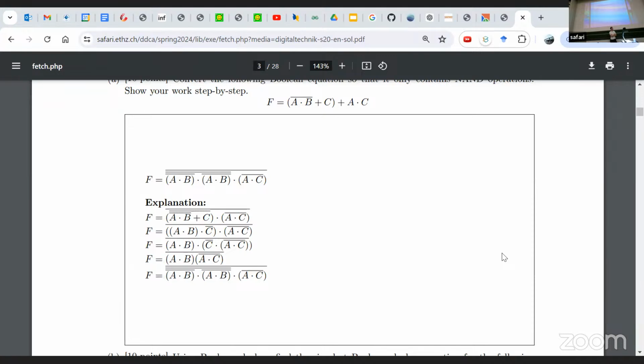So if you think about what is happening, the moment the clock cycle changes, the program counter is updated. So you have the new program counter, and here you are fetching the instruction. This comes from the memory, right? So the address comes here, we are getting it out, and now we are decoding it.